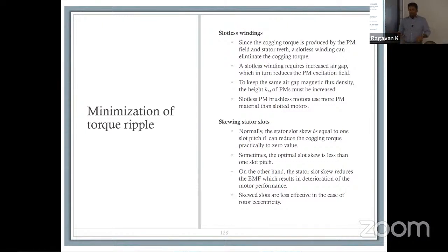PM effect. So like I said before as well, whenever you're trying to design a machine, you're trying to get all the field to go from the stator to the rotor and vice versa. Whenever you have to increase the air gap, you get some benefits in a vehicle system or otherwise. But whenever there's more gap, by definition, you're going to have more losses. So that's really how that works. So you can look at making the design have a wider air gap, but you will end up with some